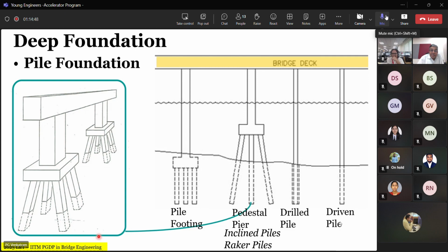So we use it in offshore structures where tidal loads are. Okay. So there, otherwise your foundations are so flexible that your earthquake is not important. I also extracted the answer from my mouth itself. You use raker piles when earthquake is not the largest lateral load causing effect.